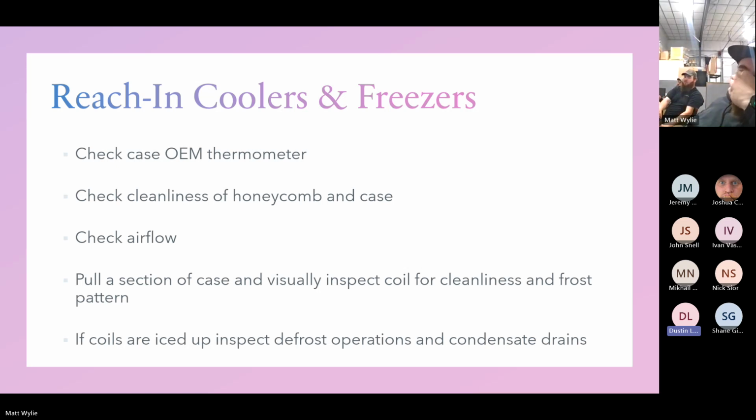Same thing with a faulty defrost. That's why it's important, when you de-ice something and you're testing defrost, to verify the electric heaters are working, but also look at the time clock and run it through a full defrost. If your time clock is a 40-minute defrost and you're terminating at 10 minutes into defrost and the frost pattern's not off your evaporator, your termination Klixon's not working correctly. So you have to really dig deep in that and verify it.